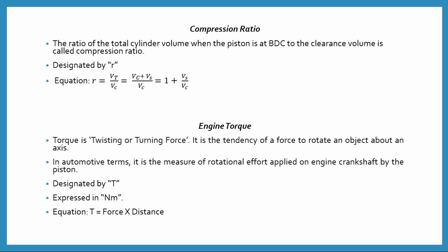Here we discuss the compression ratio. When we are talking about the compression ratio, basically it is defined as the ratio of the total cylinder volume of the piston when it is at BDC to the clearance volume when the piston is at TDC.